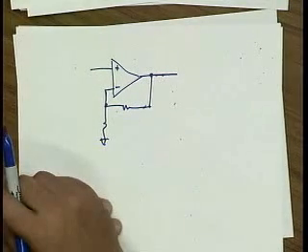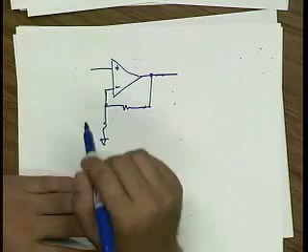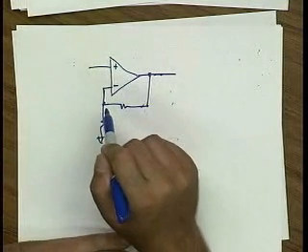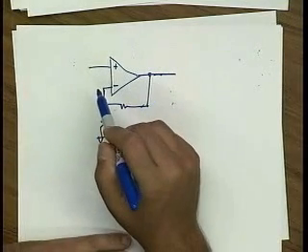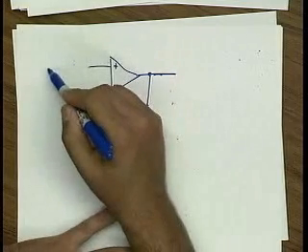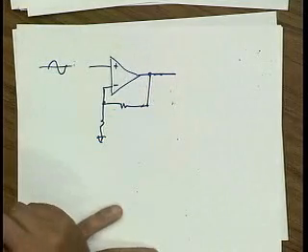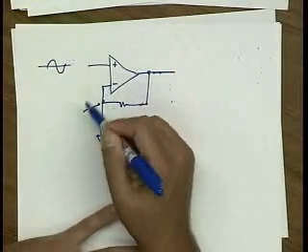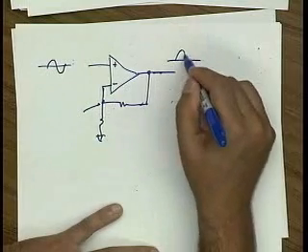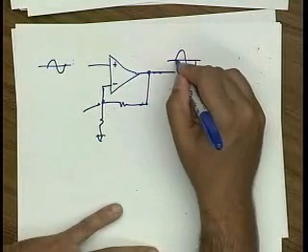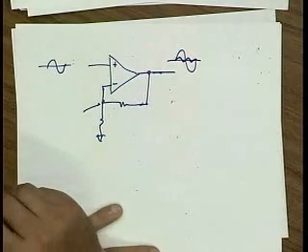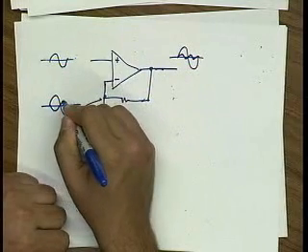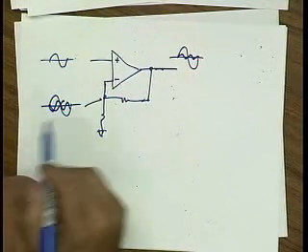What's interesting, though, is if you now look at the signal that's fed back, you'll find that the signal that's fed back to the input actually has a lot of distortion in it. Right? If I put a pure sine wave inside here, and I look at this node here, you'll find that this node has lots of distortion in it. Whereas out here, it's again clean. But let's say that you find that the distortion level here is very small, but if I look over here, I actually might find that the distortion is quite large. Can someone explain what's going on?